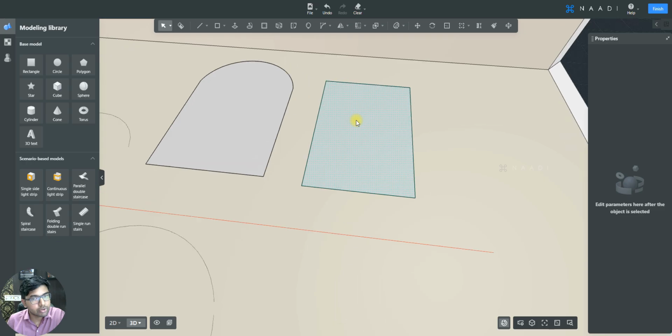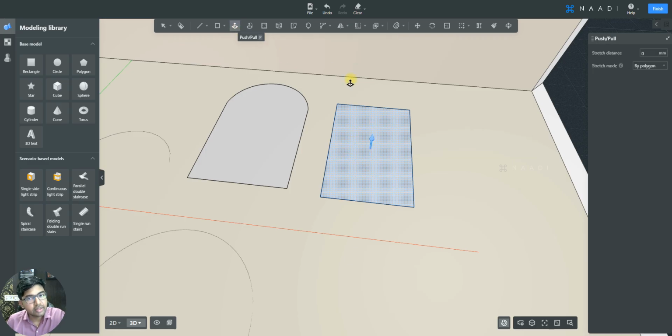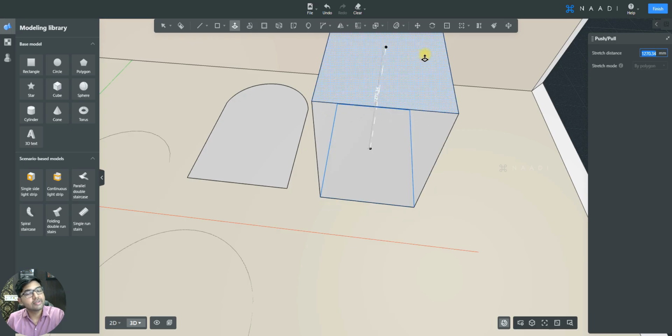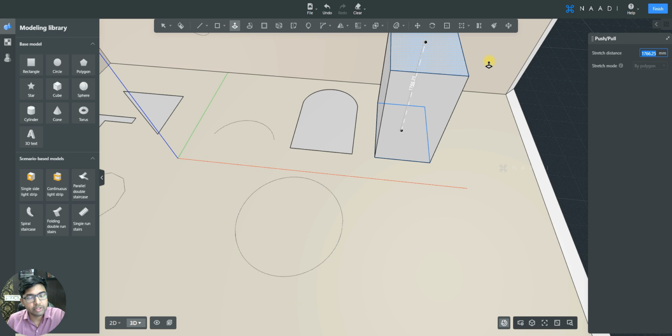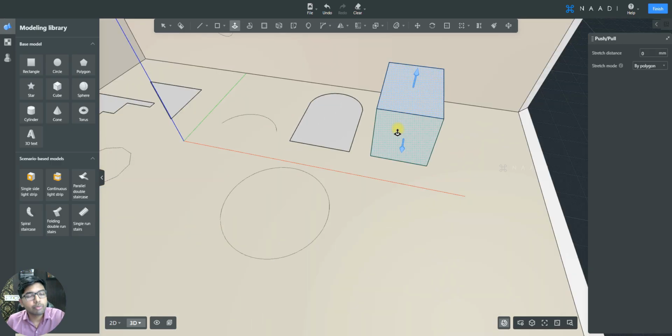So I have a rectangle tool here. If I want to create a cuboid, just select that rectangle tool, and right next to your rectangle tool in your horizontal toolbar, you have something known as push pull, right? Shortcut is P. If you click it, just like in SketchUp, you should be able to use this tool to extrude this surface. Can you see here? While extruding it, you could just click your cursor, based on which it will be extruded to a certain height. Or if you want to extrude it precisely, then in this extrusion process, just type in for how many units you would like to stretch it. In my case here, I would like to create a cuboid which is 1 meter in height. So I can just type it as 1000 mm, press enter. Now can you see here? A cuboid is created. This is one important and most frequently used 3D geometry creation tool in your custom model.